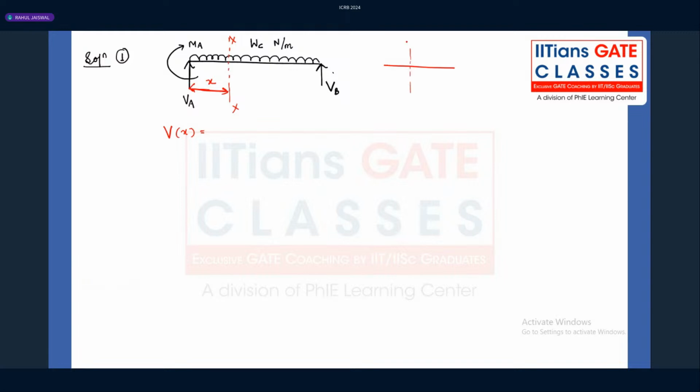We know the sign convention for the shear force diagram will be something like this. Whenever we have force like this, the shear force in section XX, whether we move from the left hand side or the right hand side, will be plus F. The similar sign convention we follow here for the calculation of shear force. VA is acting in the upward direction, so it is plus VA. There is no effect of moment on the shear force. What is the effect of WC? WC into X is the load acting. It is minus because this load for this particular part will be this much, acting somewhere here. So that is WC into X, the calculation for shear force.